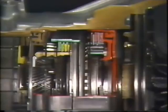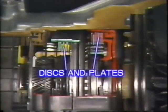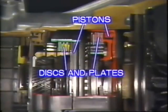Take the clutch, for example. Each clutch consists of several discs and plates, and a piston and cylinder. The clutch plates rotate together with the input shaft as a unit, while the clutch discs are engaged with one member of the planetary gear set.